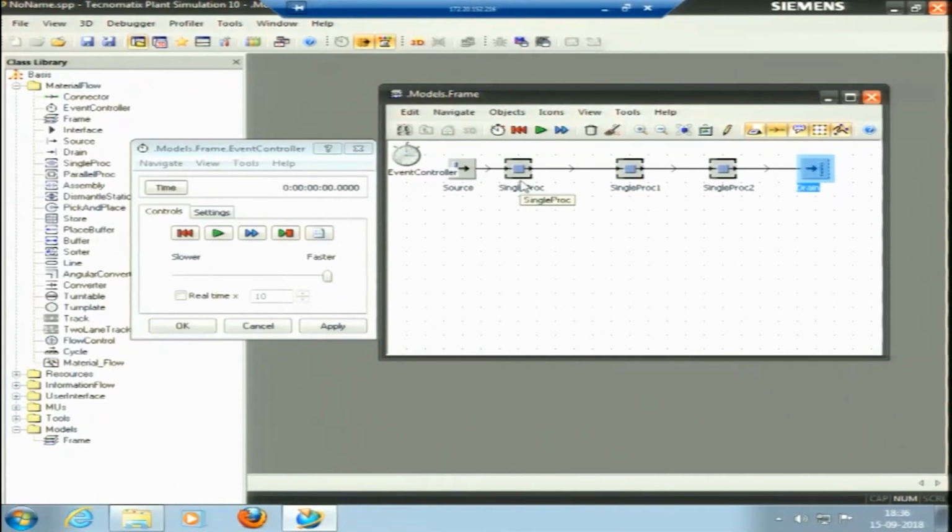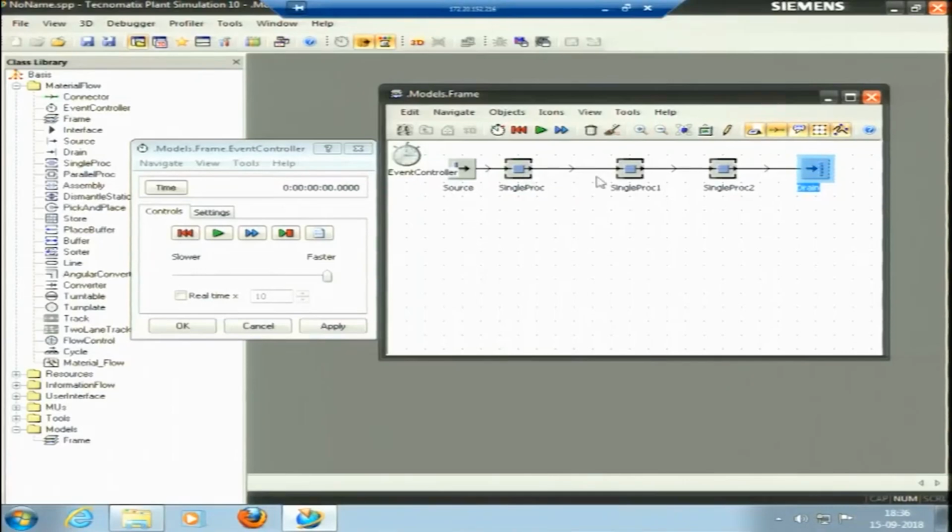This is ergonomics. If we talk about plant layout, this is work study: what is the minimum space that has to be kept. In manufacturing, the space between two machines, other than the width of the machine, is generally kept from 0.8 meter or even more, so that the workers can move in between. I have just kept it at a random location here.